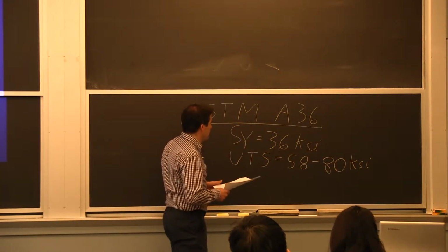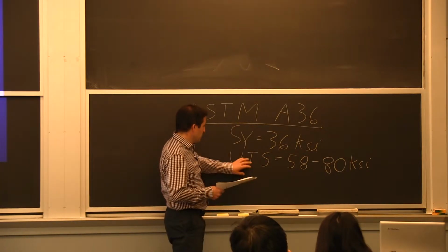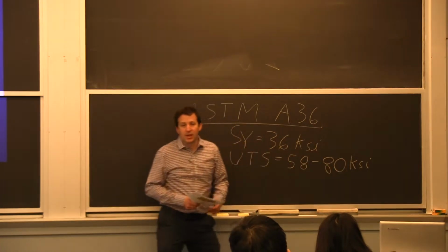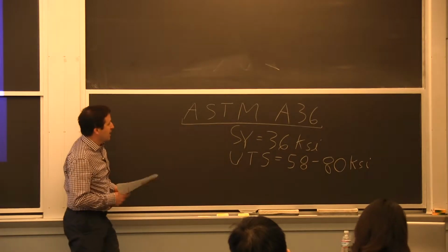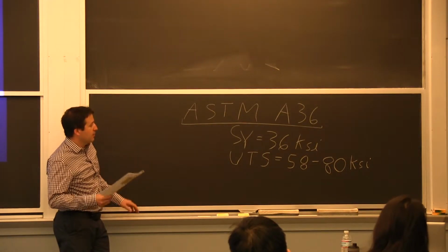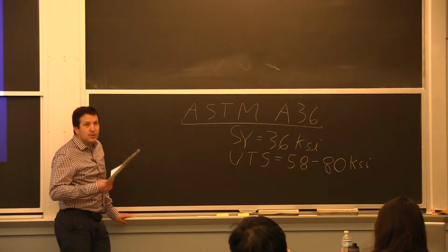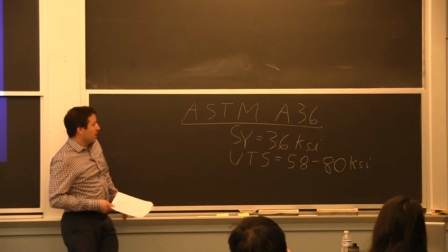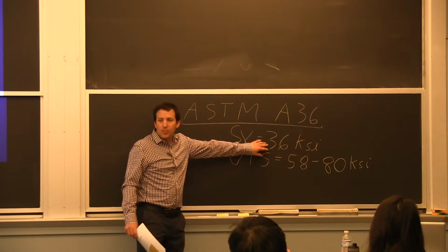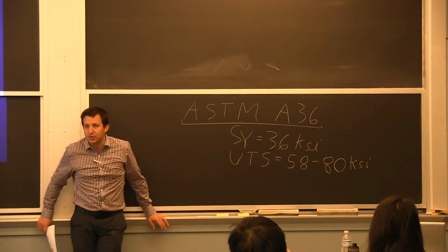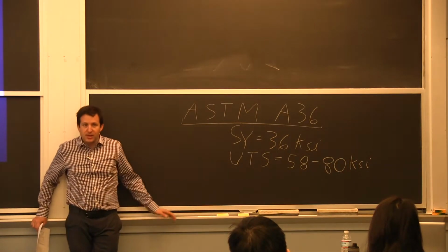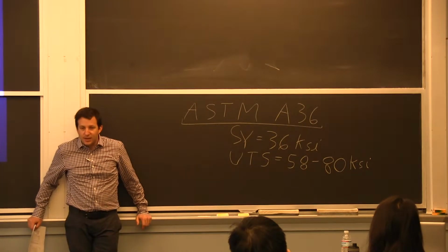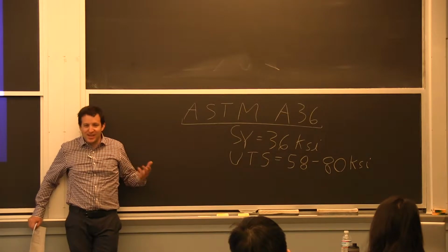The structural steel one doesn't. All it says, when you run your tensile strength, is you shouldn't be above 80. But again, if we were to take a piece of a beam from a lot of construction sites around here, I bet you we will be in the 40s, maybe even the upper 40s with respect to the initial yield strength. And it's perfectly acceptable with respect to the specification, but it's not exactly defined.